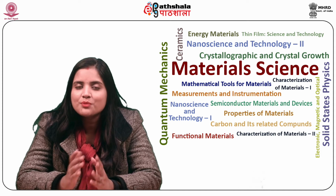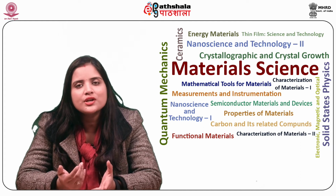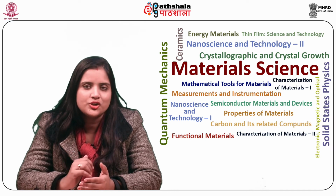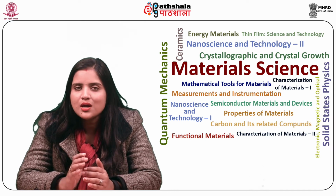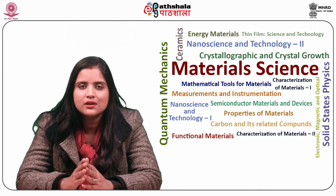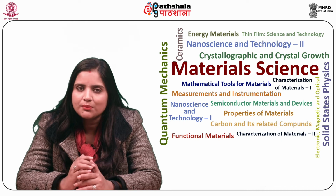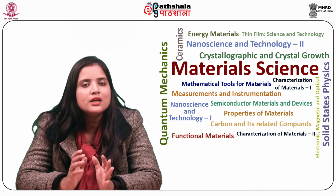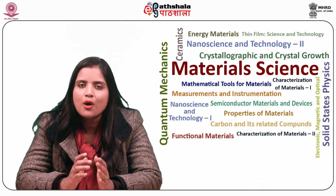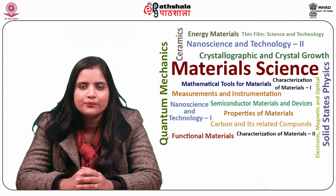Gas phase condensation process utilizes an inert gas at pressures sufficiently high to promote particle formation, but low enough to allow the production of spherical particles. Gas phase condensation employs a vacuum chamber, which includes a heating element, the metal to be converted into nano powder, powder collection apparatus, and vacuum hardware.